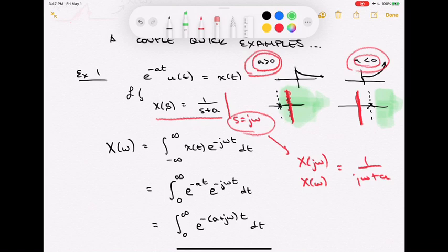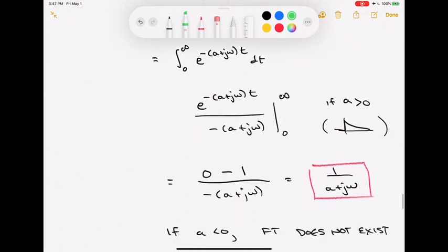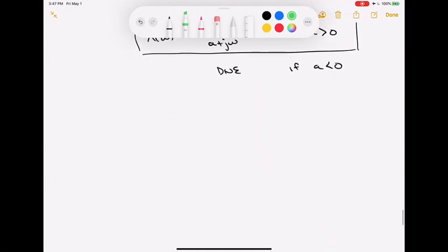We do not always get a Fourier transform existing for these causal exponential signals. So in some respects, you might think that Fourier is not quite as strong. It's not quite as capable as the Laplace transform is, right? It can't handle everything Laplace can because it only lives where the omega axis is, and a Laplace transform can have a region of convergence for some part that does not include that omega axis. Okay, so that was one example.